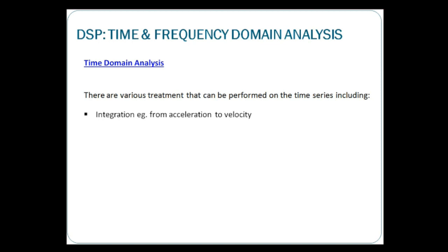The DAQ provides a constant current, 2 milliamp, to the amplifier itself, the preamplifier itself. So you have a very good signal coming in and connecting directly to your DAQ without an external signal conditioner sitting in between, right? Then coming in, you are measuring accelerations, of course in millivolts, and you have this sensitivity, then it basically converts to the accelerations.